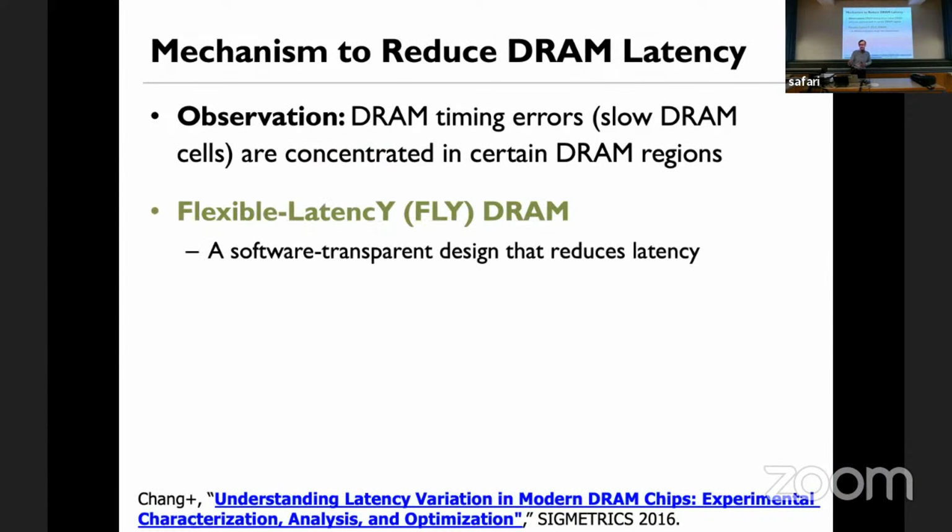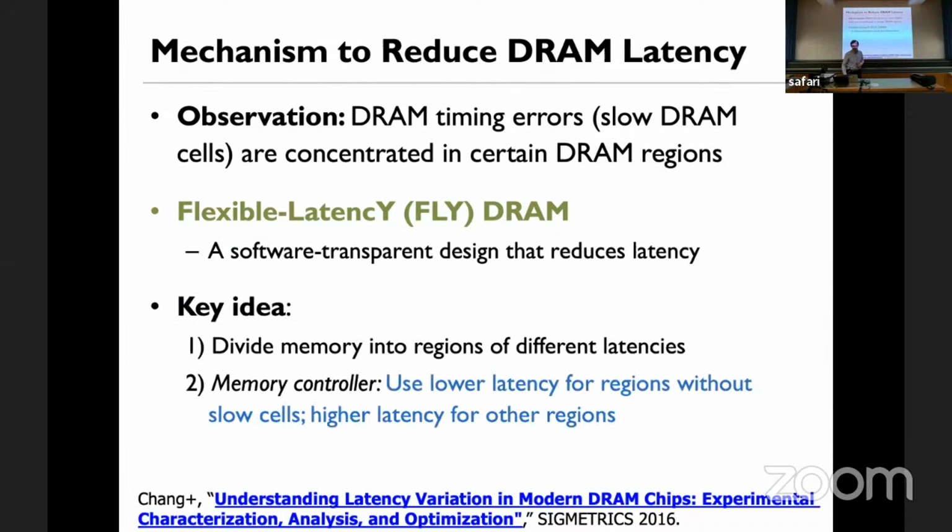And it proposed a design that's called flexible latency DRAM, FLY-DRAM. It's essentially a memory controller-based design. You divide the memory into regions with different latencies, and the memory controller uses lower latency for regions with fast cells and higher latency for other regions.